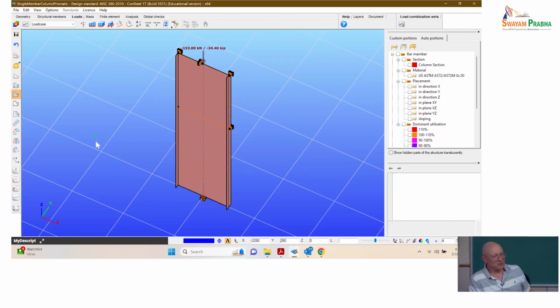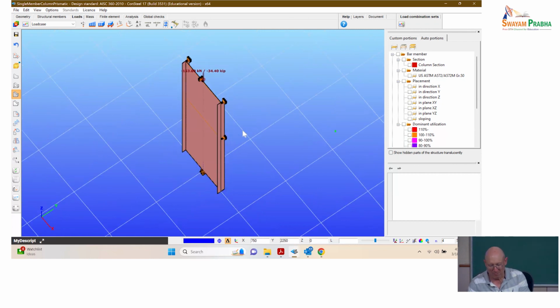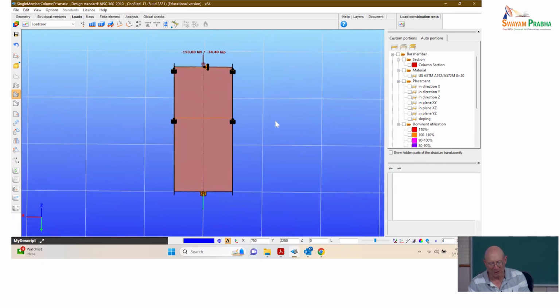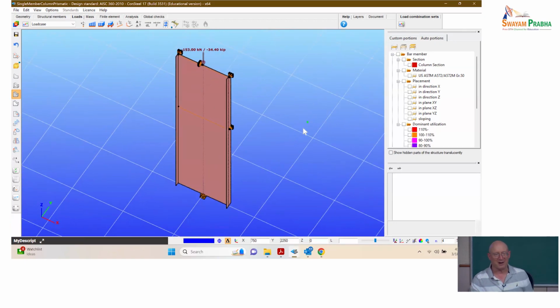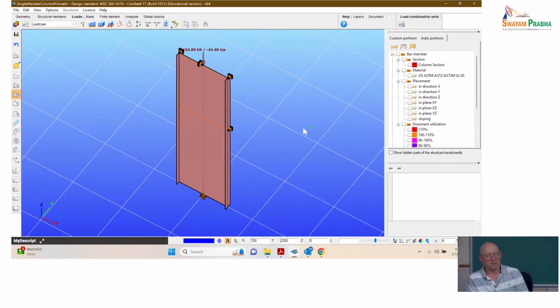To get started, the base of that frame sure looks awfully wide. How do we make that a simply supported base? Not very easily. But we're going to say that's a perfectly pinned base, and we've got the supports. Instead of it being tapered, let's first suppose that we had this member and we want to check its axial compressive resistance, using the cross section that's defined in the frame at the bottom of the knee.